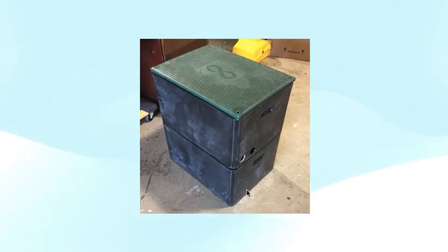This picture, just briefly, shows the reverse flush headworks that we want on top of the tank. We realize that to be able to service this headworks, we want to make sure that the lid is going to be at grade. The boxes themselves that they come in are 12 inches high, or a foot high. And so if the tanks are going to be deeper in the ground from where grade is going to end up, we do provide specific, what we'll call riser lids, for our headworks.